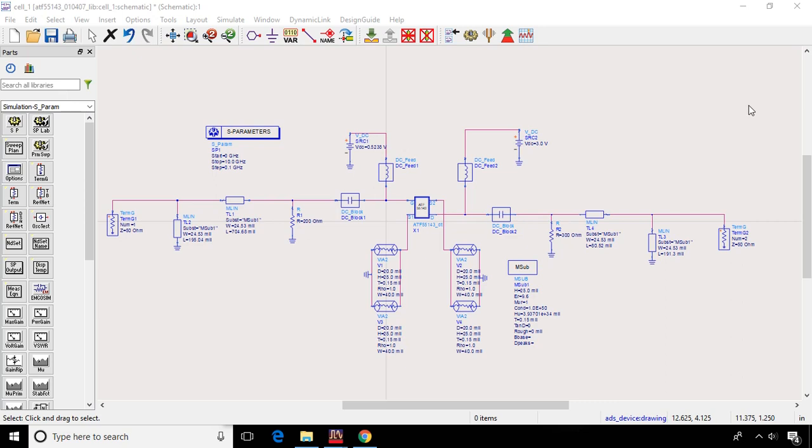For the first video, I designed the schematic layout of the whole thing, the basic principles on how to design your stub matching networks for the input and output of the low noise amplifier, and also stability resistors and reflection coefficients to design the best optimum source reflection coefficient to use for the best noise figure for your amplifier.